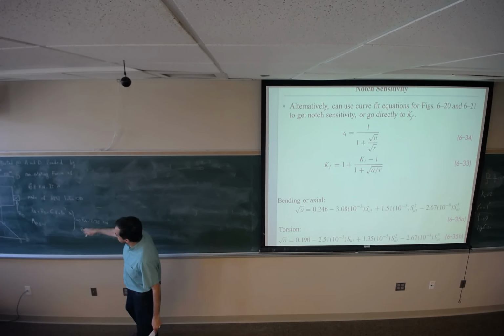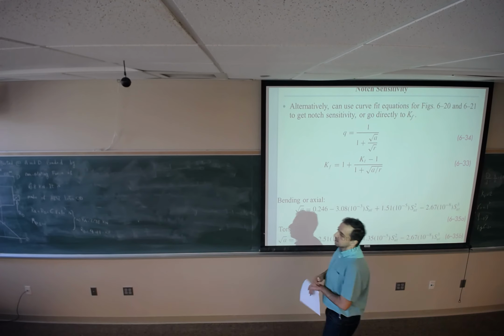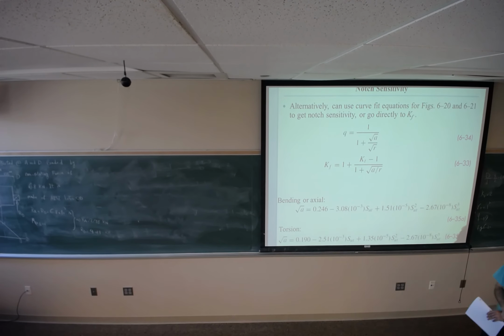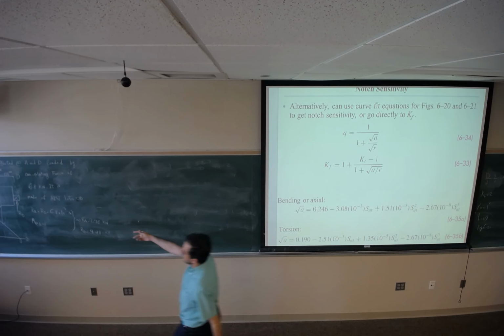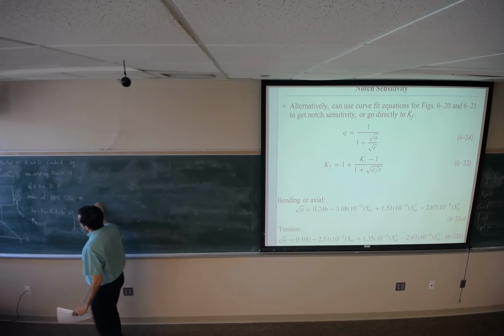I just skipped this equation. I didn't write it down, but you can write the bending moment at point A and set it equal to 0. Two equations, two unknowns, solve for RA and RD. Now,